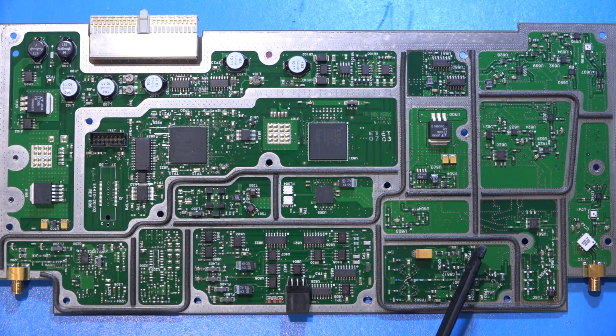So I think a good place to start is to connect this to the spectrum analyzer, see what the PLL is producing, connect these guys to the oscilloscope, and see the correlation between the frequency tuning and these, and see if we can debug and reverse engineer it. We might also take some X-rays of this region so we can take a closer look at the VCO as well. So I think these are pretty good places.